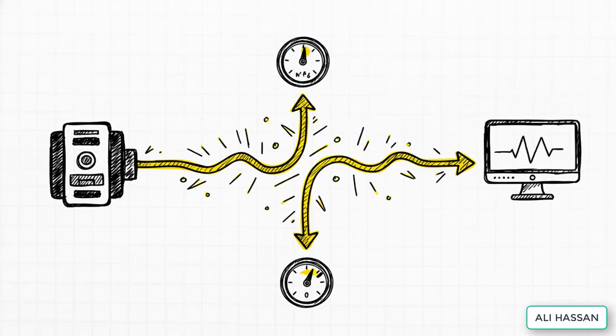And it's not just any old signal. It uses this really elegant industry standard, a 4 to 20 milliamp electrical current. Now, this is a huge deal. It means that pretty much any controller from any company can understand what it's saying. 4 milliamps means zero pressure, and 20 means you're at the max.